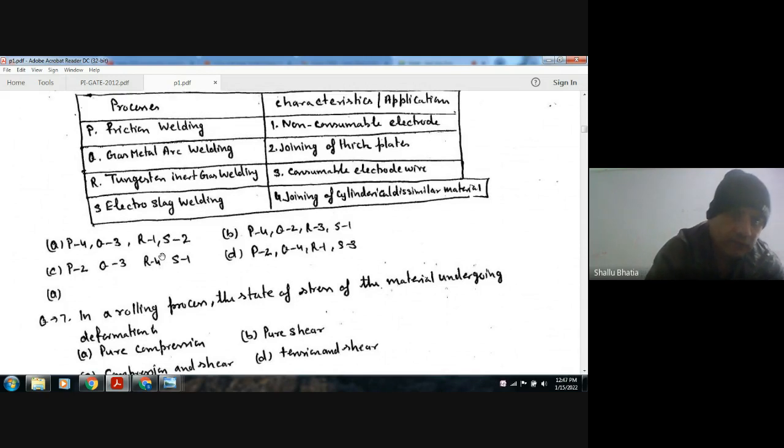Okay, the right answer is A, because friction welding is used in joining of cylindrical dissimilar materials. Gas metal arc welding, that is MIG, uses a consumable electrode. TIG uses a non-consumable electrode. And electroslag welding is used in joining of thick plates.